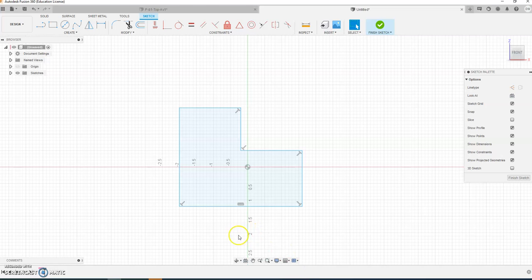It was still blue. Well, the reason is because they made a mistake when they were first drawing it, and they deleted out this original line here. When you delete out that original line and then draw it back in, notice what happens. That line goes back, the perpendiculars show up, but that parallel constraint to the origin is gone now. Without that there, their drawing could just spin and rotate on the screen, and it wasn't staying constrained. So the solution here is, what you need to do is pick your horizontal and vertical constraint, click on this line, and then again it puts in that constraint, locking it horizontally to that origin. And then that's great, and it's good to go.